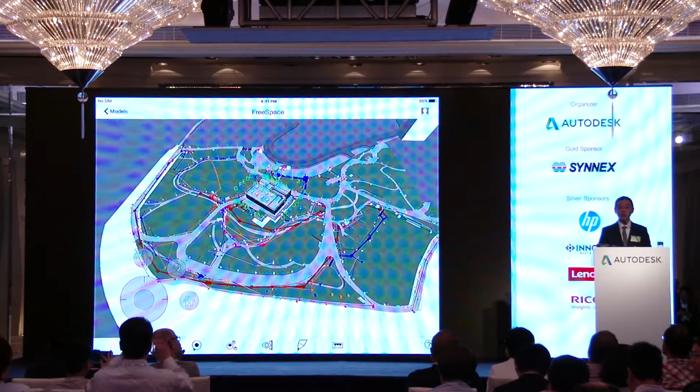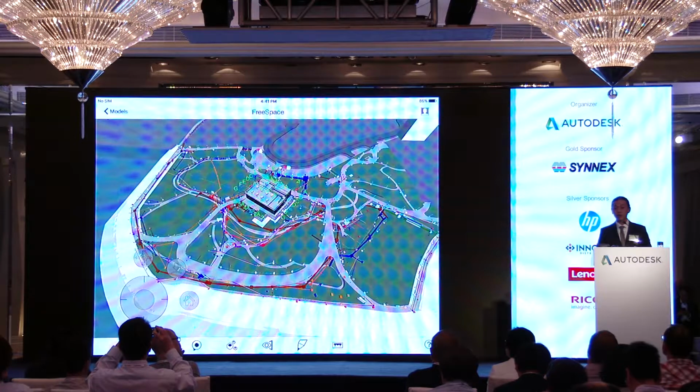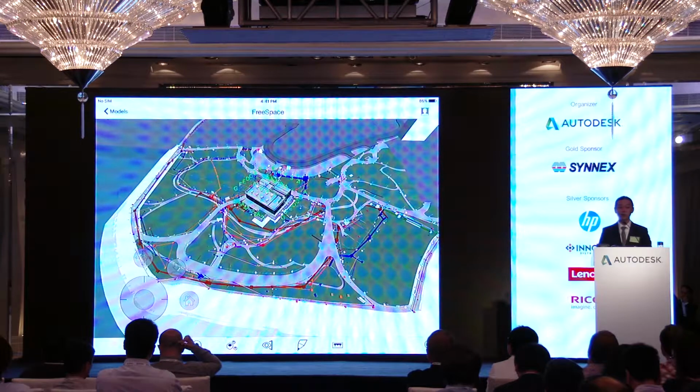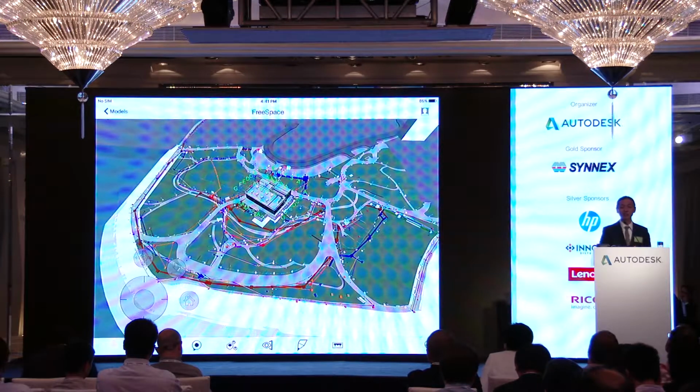And the underground utilities are done in Civil 3D. The building is done in Revit, and we've been using Dynamo and various other software. But Glue can take a lot of different file formats as well. So basically, I glue it all up here and run Clash with it. It doesn't matter if it's Civil 3D or Revit or whatever, just run Clash here, it's fine.